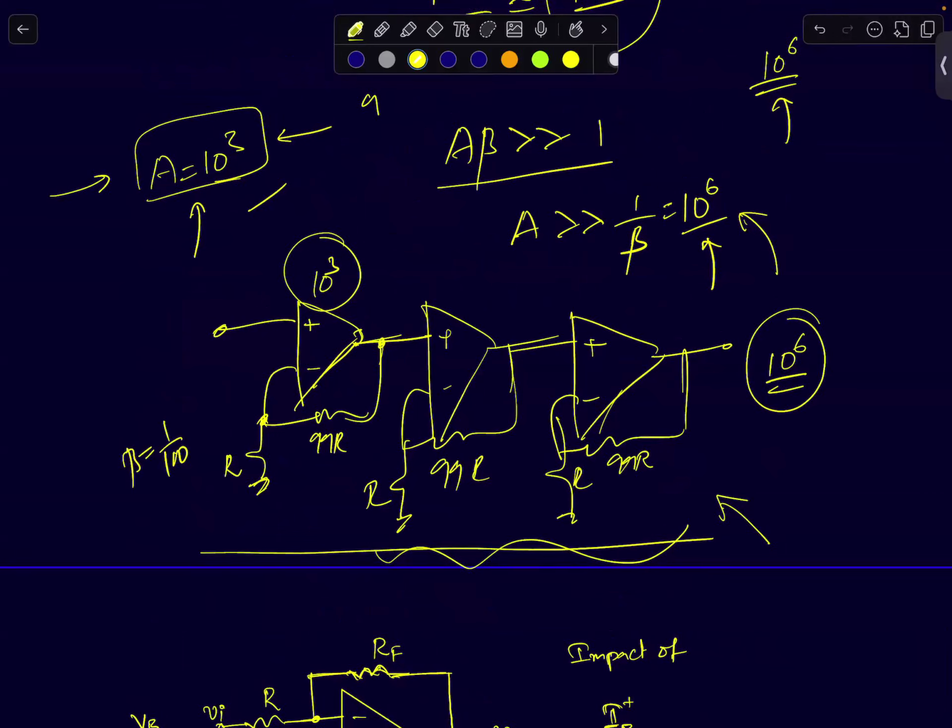Sometimes your sensors can generate microvolts of signals. And let's say you have to interface it to an ADC, which is operating in volts, maybe a few volts. Then you will have to amplify that by at least 10 power 4 or 5 to bring it to volts level. So these are very niche applications where you have weak signals which need to be brought to volts for digital processing, for example, the ADC might be sitting inside a microcontroller, and you may have to put this before that.